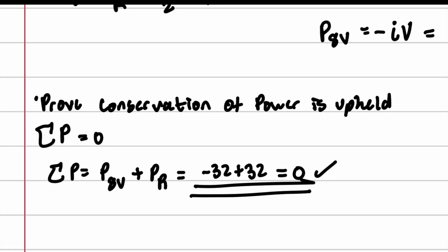If you have the chance, always, always, always check power and see if the sum of all the powers equals 0. That will save you a lot of mistakes on exams.